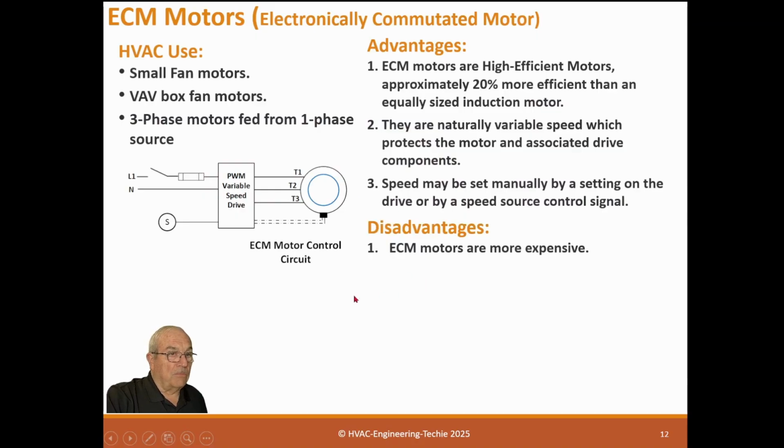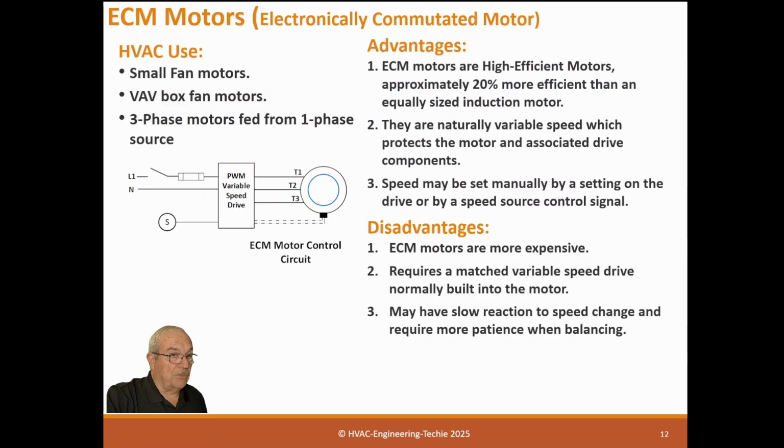Disadvantages: ECM motors are more expensive, obviously. It requires a matched variable speed drive normally built into the motor. May have slow reaction to speed change and requires more patience with balancing.